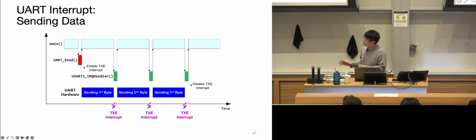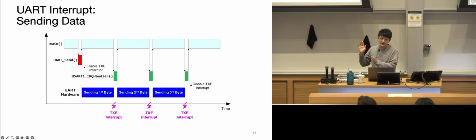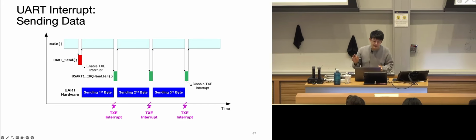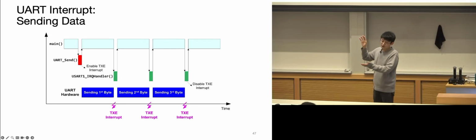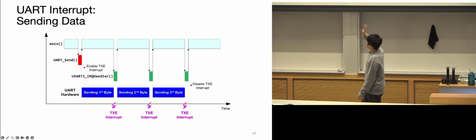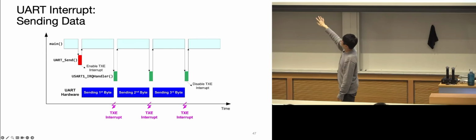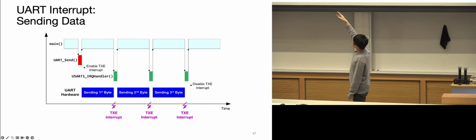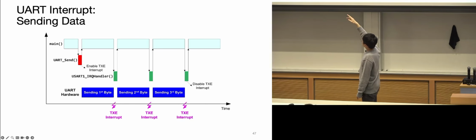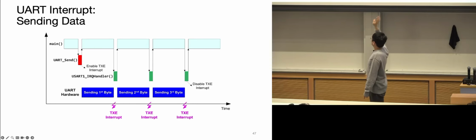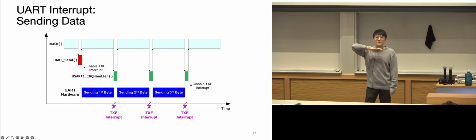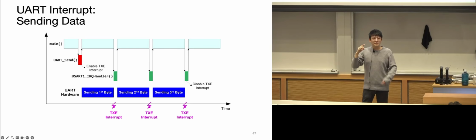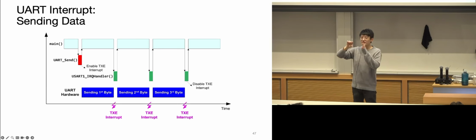And chances are we're going to have a bunch of these data frames come in, right? Whenever there's a UART send triggered, because it's usually a string, it's going to just start sending the first byte and do a quick interrupt, and then send the second and the third. And usually this is done, hope you guys still remember, with the processor always staying in handler mode.